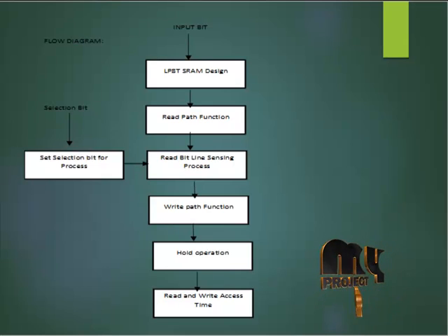In our project, we compare with the other RAM cells and main memory access. The speed of memory has seen a large increase, and there is a gap between the performance capability of memory and the processor. We reduce the supply voltage, so dynamic power decreases and first order leakage power decreases, while operating the cell in the subthreshold region, with a supply voltage below the threshold voltage.